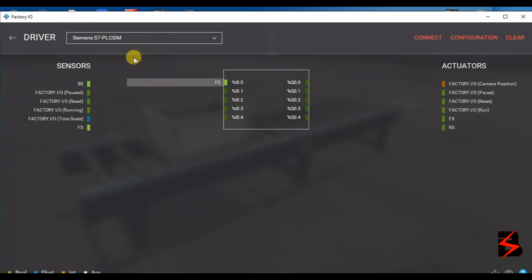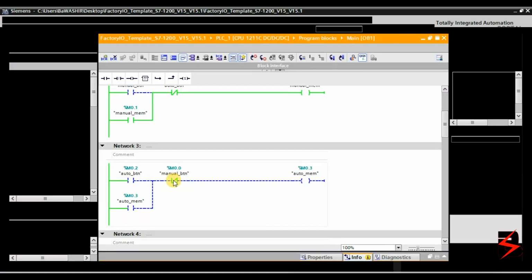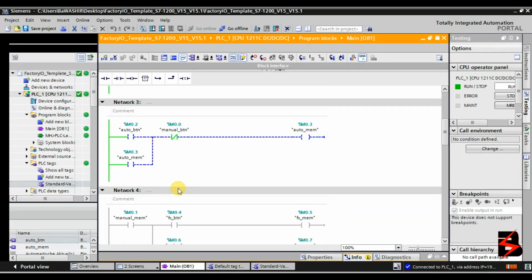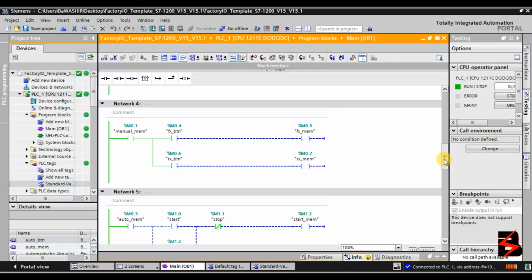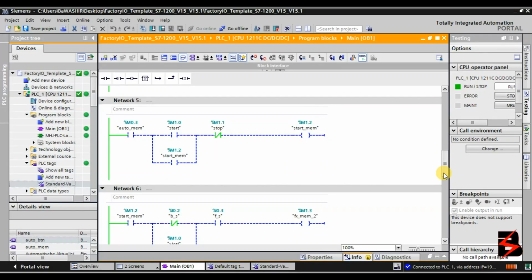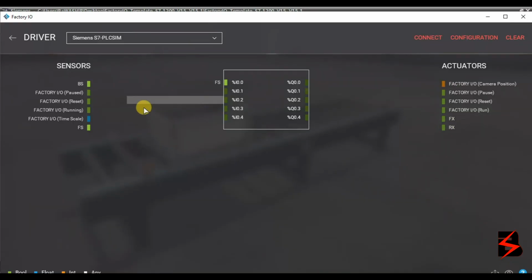So now we have to connect. Remember FS sensor, we started from, let me check my ladder. Where were the sensors? Because I have only 2 input sensors and 2 outputs, reverse and forward. So forward sensor is 03, back sensor is 02. Okay. Back sensor is at 02. You see they are normally closed, they are red lighting. And forward sensor is 03.